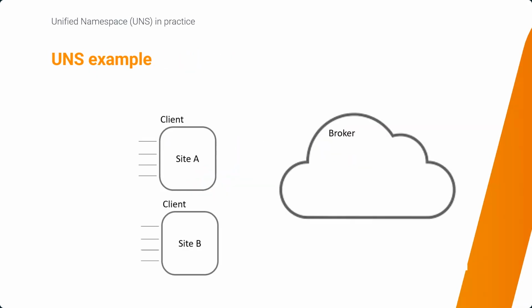Whenever taking a look at how the broker and a client works, I use this slide here. So we have 2 clients, site A and site B, and we have 1 broker. So let's say site A is sending data to the broker. So this is publishing data to the broker. And whenever some data is being published to the broker, we define a topic, which is actually the name of the data point. In this case, it's site A, and a tank level.